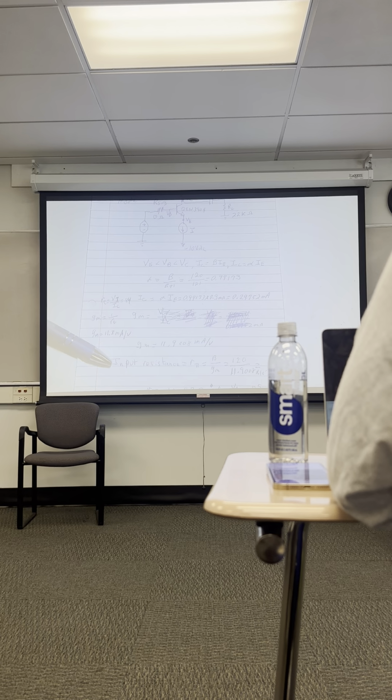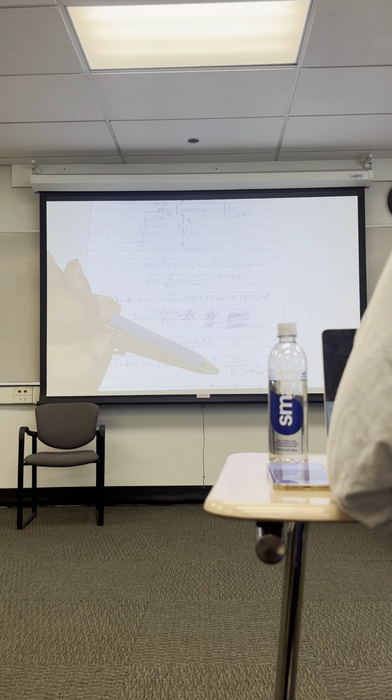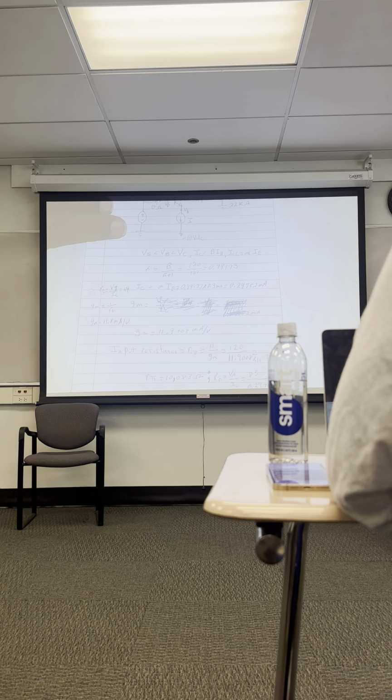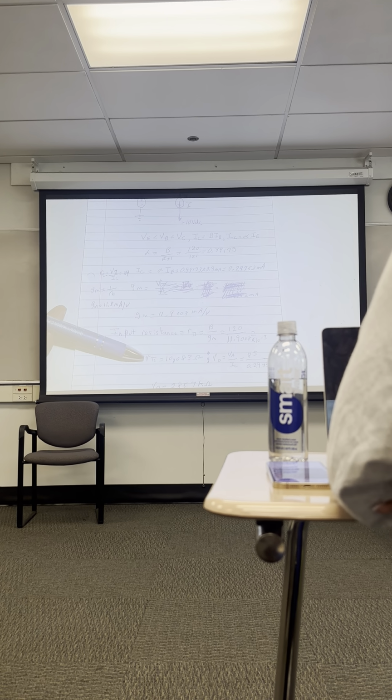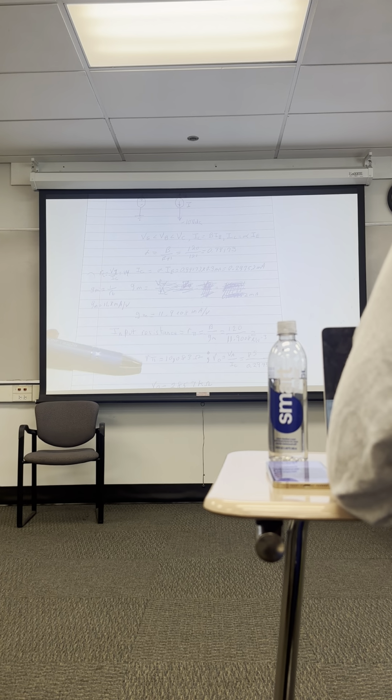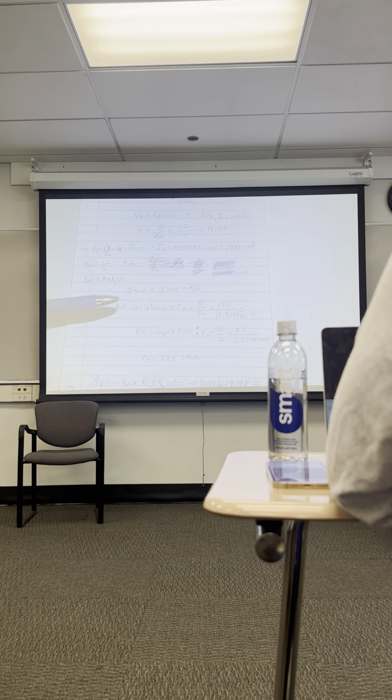So that's 120 over 11.9 times 10 to the minus 3, and that means R pi is about 10,000 ohms. The only voltage given, I believe, is 85, so R sub O is V sub A over I sub C. So R sub O is a large number, approximately 285.7 k ohm.